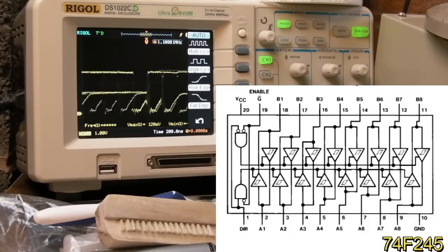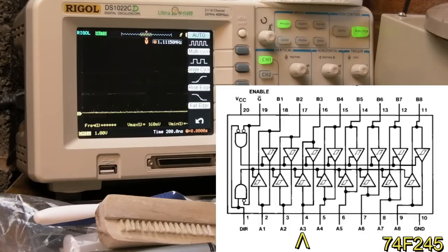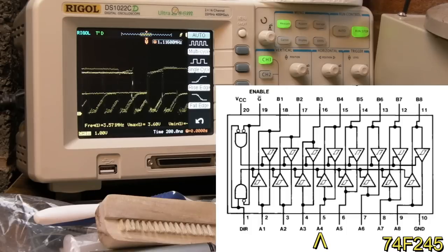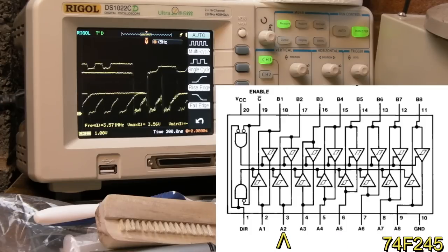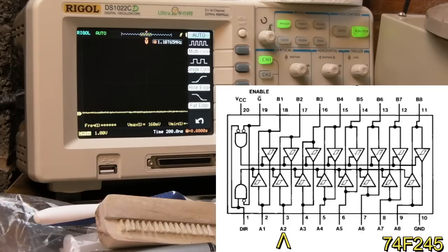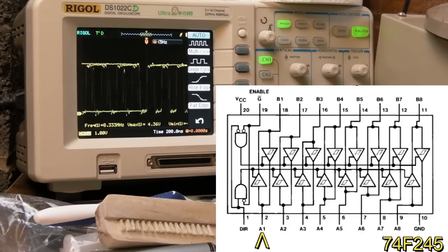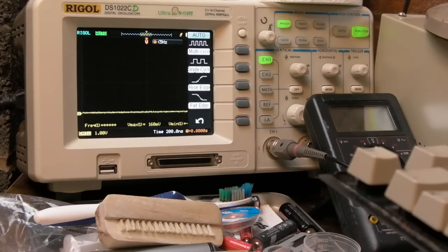I'll check pin 4. Bear in mind these are the data bits. Going up the chip, these all look the same, but that first one, pin 2, doesn't. So I actually think it's not passing a bit on that side. So I think that 245 needs to come off. That's the next thing I'm going to do: remove that 245.